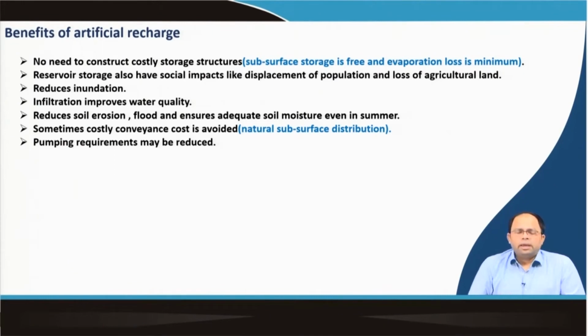So now that we are talking about artificial recharge, instead of storing the water on the surface, let us see what the benefits of artificial recharge are. So first of all, there is no need to construct costly storage structures. That means we usually create dams in the river, and we also create large water bodies with lining and all. So we reduce on those costs. Why? Because subsurface storage is free and evaporation loss is also minimum. So usually the effectiveness of subsurface storage is much better. Storing the water in the ground is actually better than storing it on the surface.